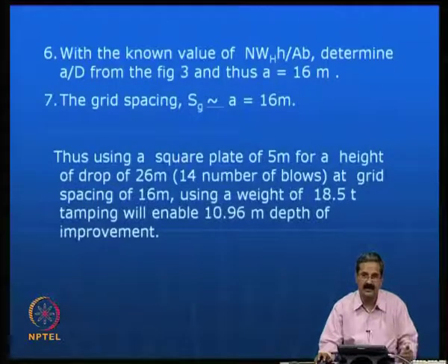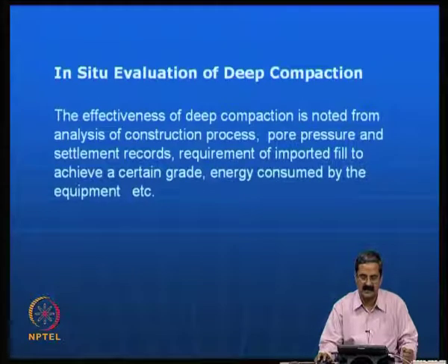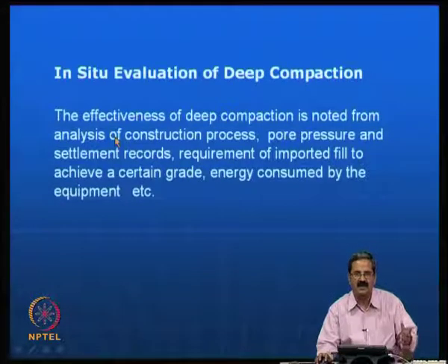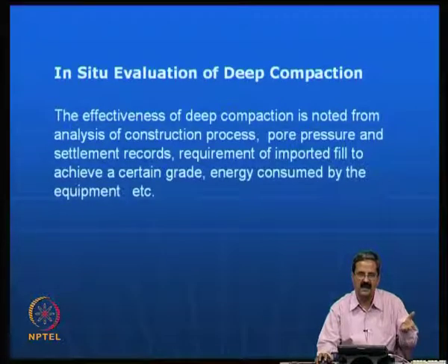So, one can check and then come out with a simple design. As I just mentioned, the design is a very simplistic design, and the best thing is that you have to verify how correct it is, to what extent this deep compaction is effective. So, what you do is go for in situ evaluation of the deep compaction methods, and the way we do it is that you try to analyze the construction process itself, like how the process is designed. With the calculation procedures we have seen, we can do a parametric study on that and work out a proper construction sequence.